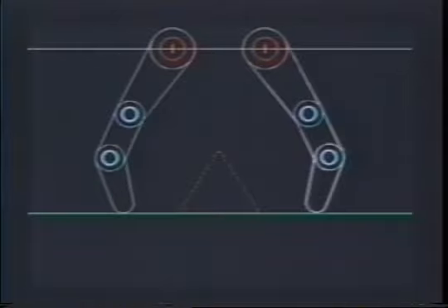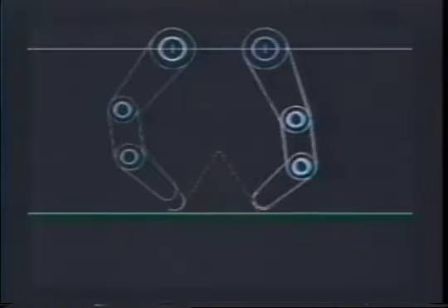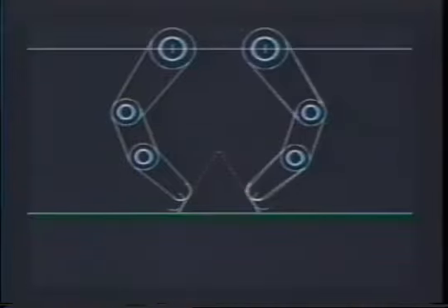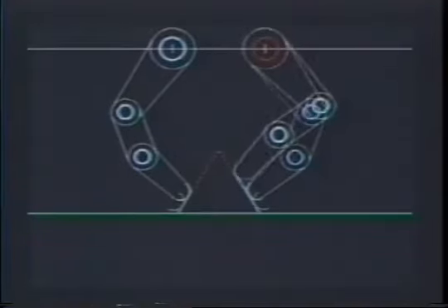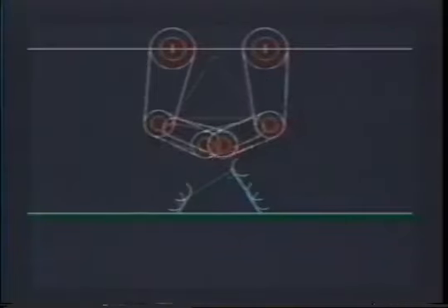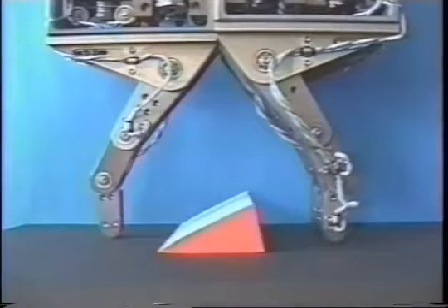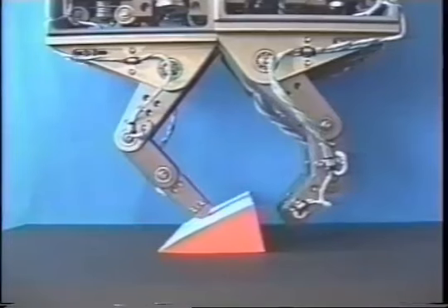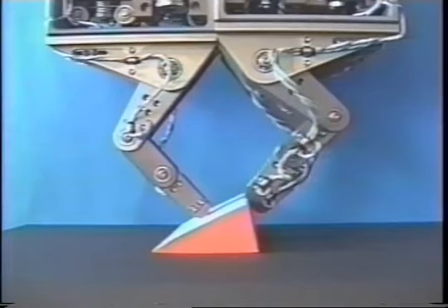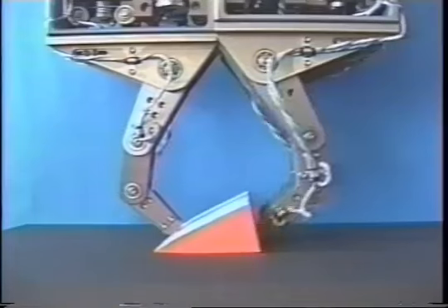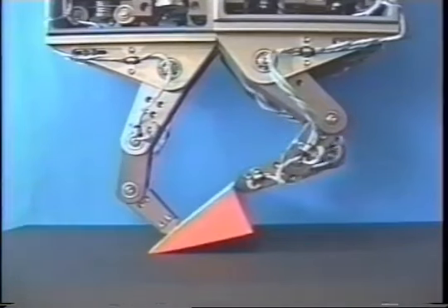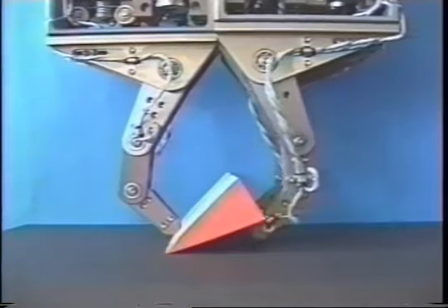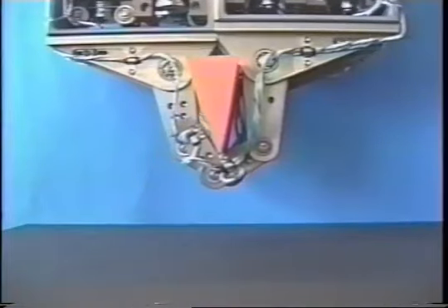By dual contact motions, the finger detects the object's width and the local slope. The goal of the active sensing is to detect the pushing point for rotation without any tactile sensor. To do this, one finger is traced over the object's surface until it detects the point where a normal force can generate a rotating moment. After detecting the pushing point, the finger rotates the object such that the fingertip can be inserted between the object and the table. Then, constant torque command is sent to each joint for the target grasp.